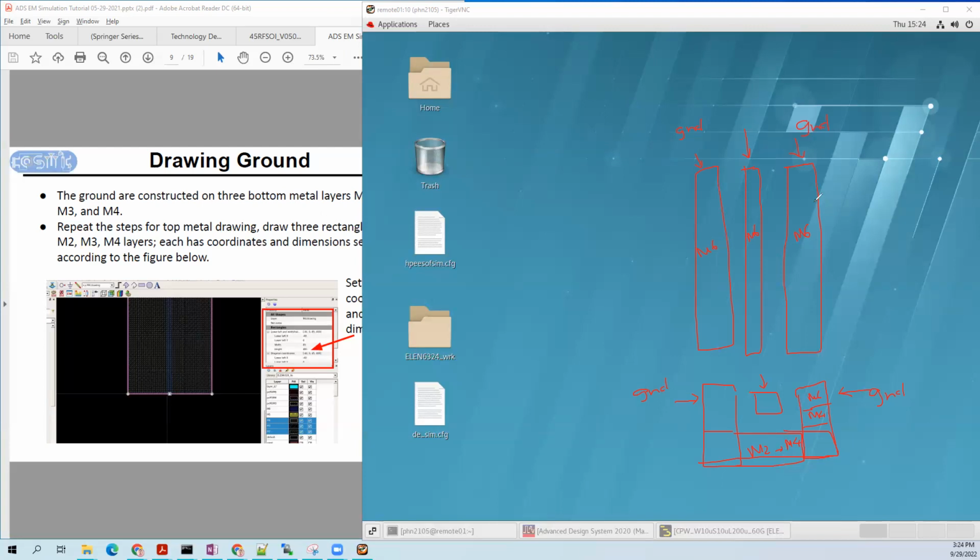Yeah. Okay. In general, true, but you can also play around with the spacings as well, because the characteristic impedance of the transmission line is the square root of L over C, right? So this C is going to depend on the spacings.